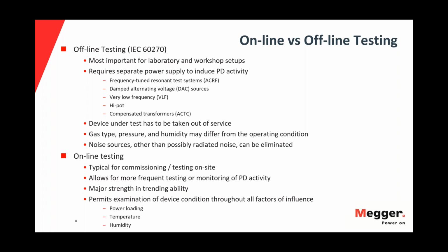Basically, offline tests give more accurate and more control over measurement of partial discharge testing due to the lower noise and calibration and control of the high voltage source. However, not to forget the benefit of online testing.